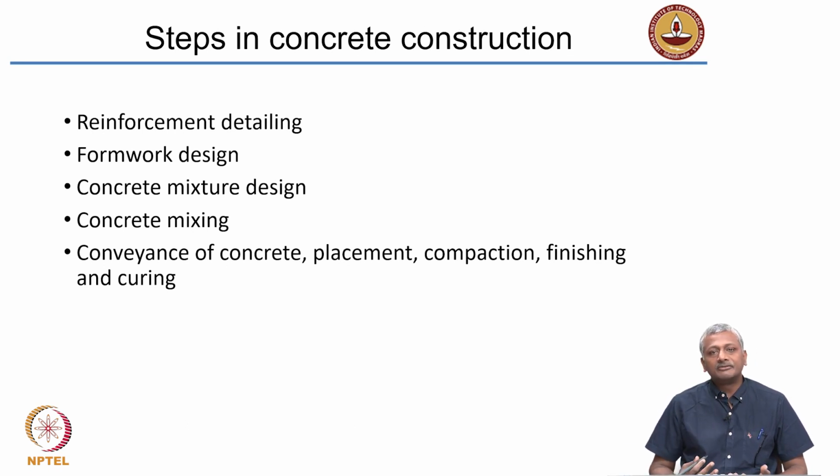that they give a concrete mix that has a sufficient amount of workability, and of course it performs to the satisfactory level in terms of strength and durability. Now the process of mixing itself is important because ultimately these ingredients that you put in have to be intimately mixed together to give you a composite material that is having a uniform spread of different phases across the volume.